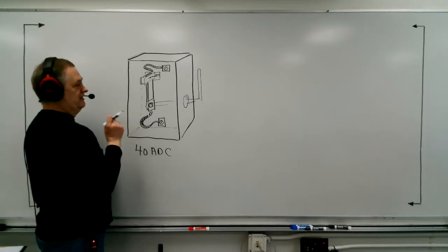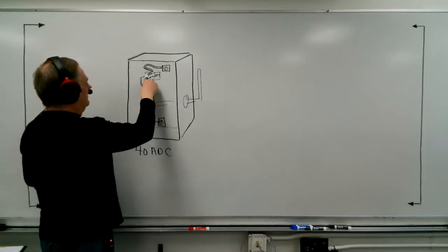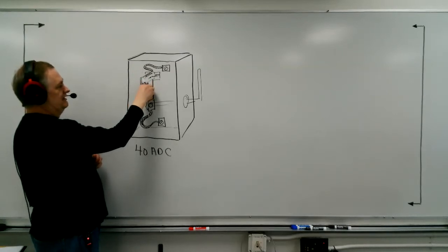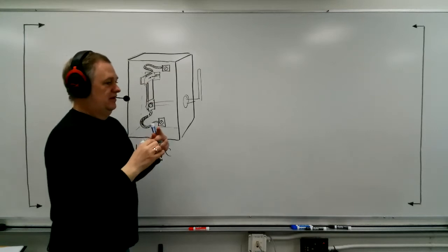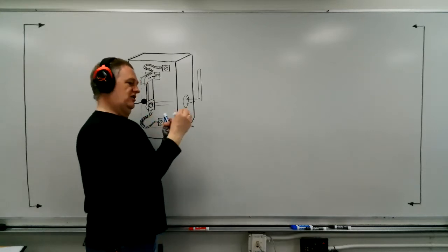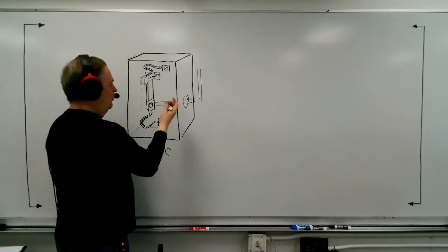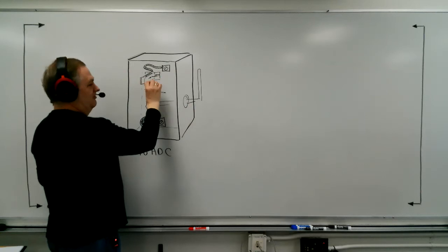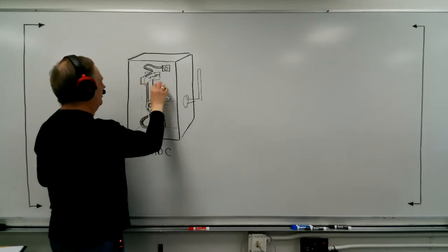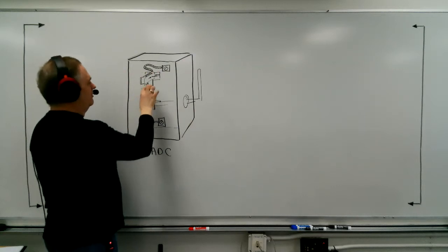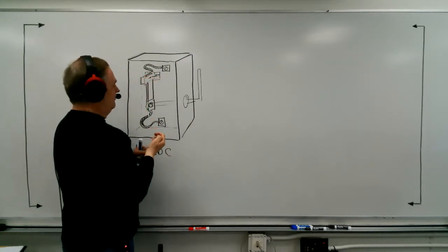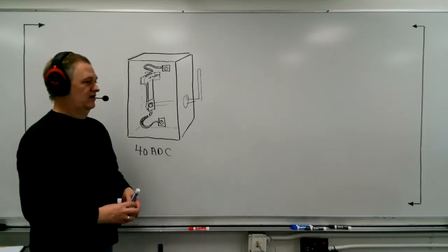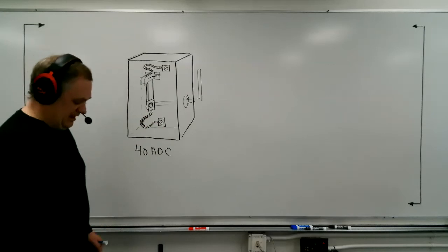One of the problems with DC current when you try to break it is that as the blade leaves the jaw, very often there will be an arc drawn. An arc is a little bit like welding in some ways, so it can create spits and tiny particles of molten metal, and it roughens the contact and raises the resistance. So there's lots of maintenance involved with DC switches, plus their physical size is very large. That's about a 40 amp mechanical switch.